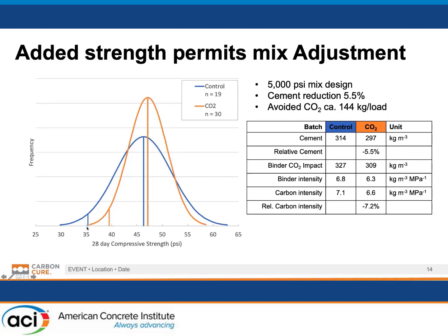They're concerned about the strength at the bottom end, where they can be 95% certain that the batch of concrete that goes out will be stronger than the strength that's needed for the job. So if you're doing something that gives you stronger concrete, you can make an adjustment to give you, again, strong enough concrete.